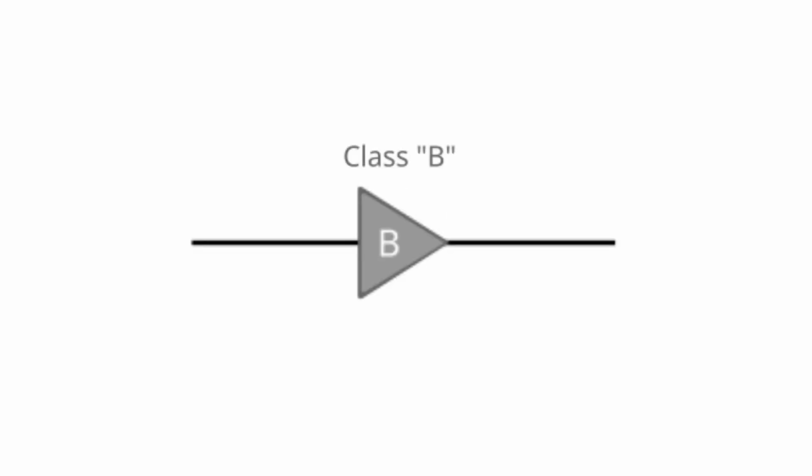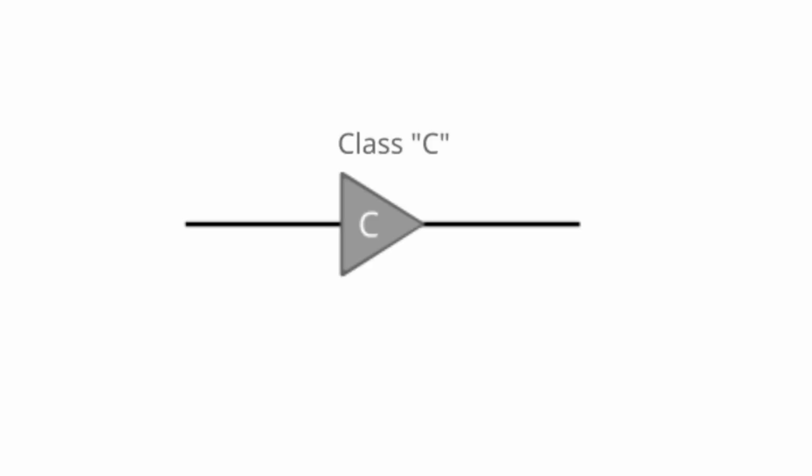Power amplifiers can be divided into three main classes. Class A provides the least distortion, but is the most power inefficient. Its average efficiency is always below 25%. Class B is more efficient, with efficiency up to 70%, but for better efficiency there is a cost: higher distortion. Class C is the most efficient power amplifier, with efficiency up to 80%, but it provides high distortion that makes it unsuitable for amplifying low frequency signals. It is mostly used in radio frequency applications.